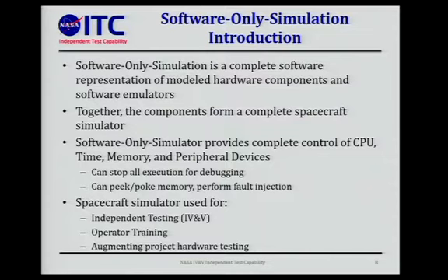Some of the advantages of software-only simulation is that it provides complete control of the CPU, the timing, the memory, and the peripheral devices. And this is where things get kind of fun because we can stop execution at any time. We can stop all threads of the flight software. We can peek memory. We can poke memory. We can perform fault injection very easily. We don't have to break hardware to do fault injection. We can simulate that with our simulator and inject any fault that you may be interested in.